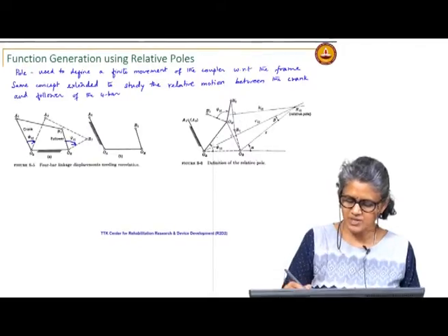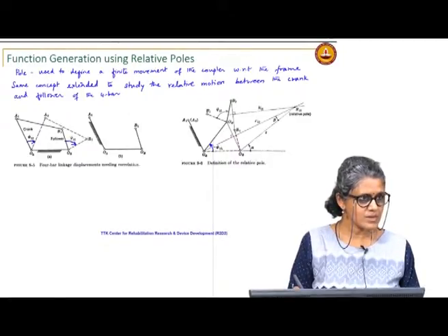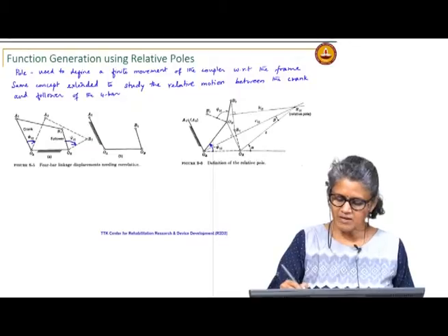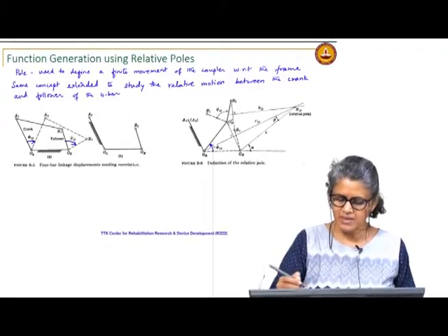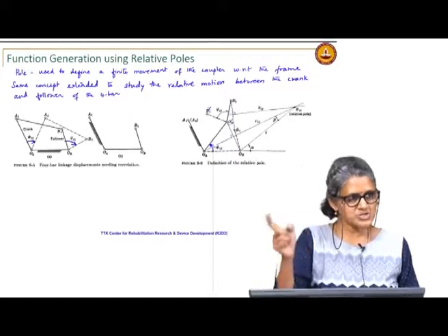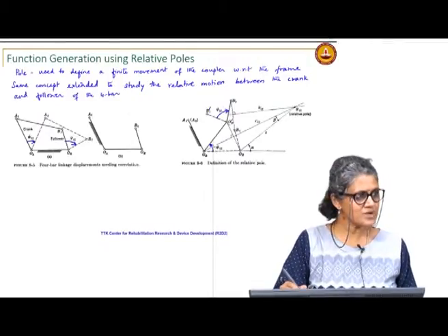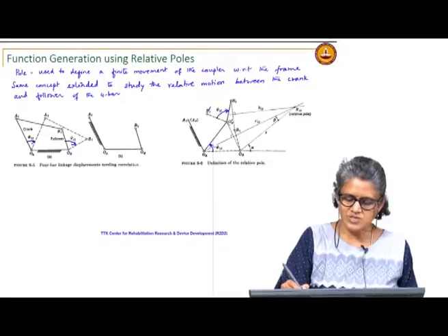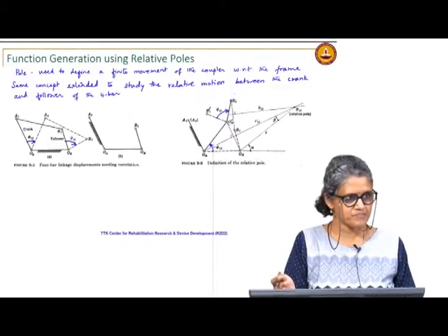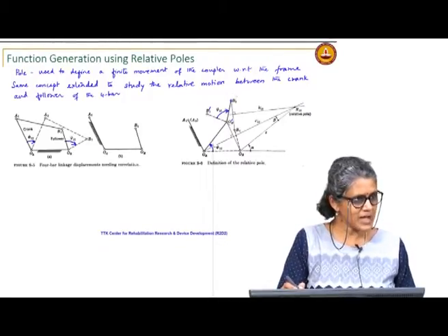first rotates by minus phi 1 2. I rotate by the angle minus phi 1 2 to bring the frame close in the second position, and then this is OB dash, and initially B1, if I move this as a rigid body, it goes to B1 dash, but OB B1 dash should actually have moved a psi 1 2 in the second position. So, this becomes my B2 dash. This is what we did last class with the inversion. So, B1 moves to B2 dash,